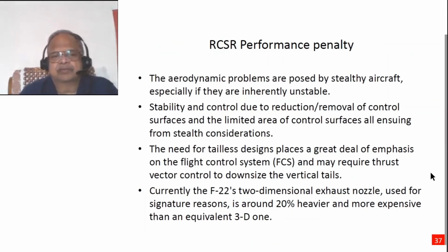The aerodynamic problems posed by stealthy aircraft, especially if they are inherently unstable: you want to ensure that the instability of the aircraft is minimized so that there is a lesser trim drag penalty. Stability and control suffer due to reduction or removal of control surfaces and the limited area of control surface, all ensuing from stealth configuration. So these are all challenges.